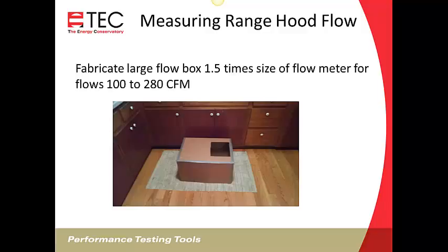If you're going to be using this on a regular basis to measure exhaust fan flow and kitchen fan flow, it's a good idea to start out with cardboard, because now you've got something you can use tomorrow with something that's readily available. But long term, it's going to be better to fabricate that out of something that's going to be more permanent. Then it's not just something that's taking up space in your truck or your car. It's something that you'll be able to use.